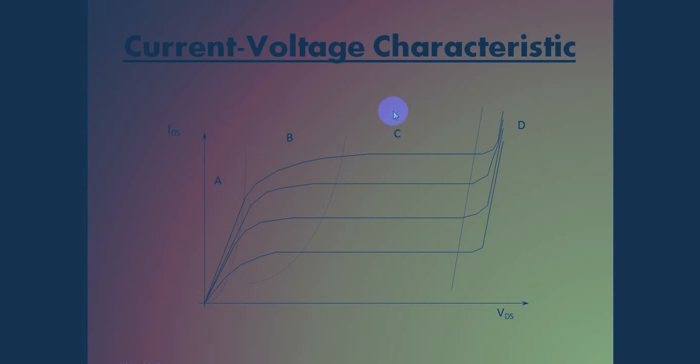The linear region and the saturation region are separated by this pinch-off voltage, which is discussed later, and the linear region at times acts as a resistor also. Along with this, we can say that MOSFETs are operated in the linear mode only for digital use, whereas the saturation region is reserved for analog circuits.